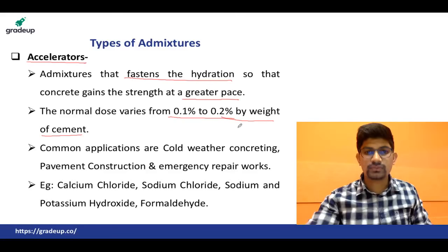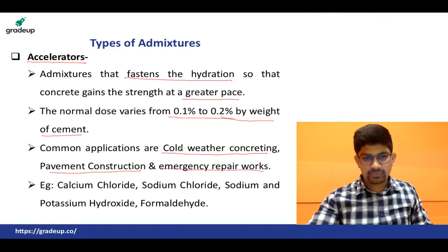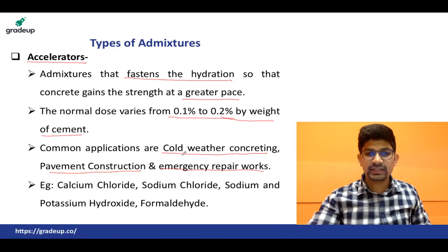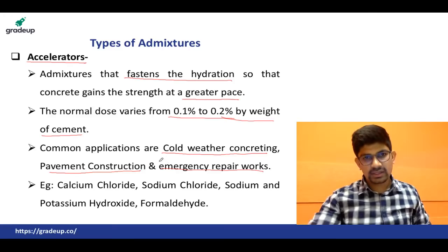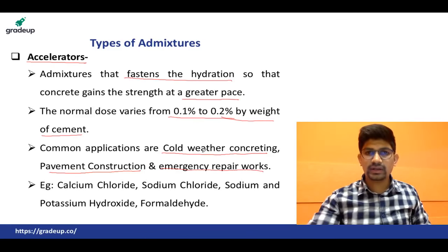Now common applications are cold weather concreting, pavement construction, and emergency repair work. Now among all these, you can definitely highlight that you require early hardening of the concrete, you require early strength development. Because in cold weather concreting, if the concrete doesn't become hard early, then it will lead to frost action. So it has to harden fast.